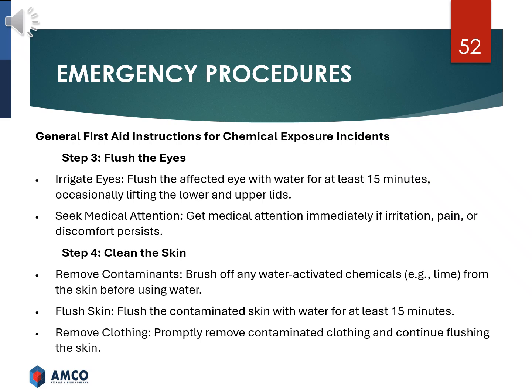Step 4. Clean the skin. Remove contaminants. Brush off any water-activated chemicals, e.g., lime, from the skin before using water. Flush skin. Flush the contaminated skin with water for at least 15 minutes. Remove clothing. Promptly remove contaminated clothing and continue flushing the skin.